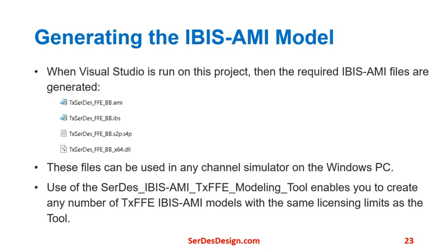When the Visual Studio is run on this project, then the required IBIS-AMI files are generated. These files can be used in any channel simulator on the Windows PC. These are the AMI file, the IBIS file, the S4P file, and the DLL file. Use of the SerDes IBIS-AMI Transmit FFE Modeling Tool enables you to create any number of Transmit FFE IBIS-AMI models with the same licensing limits as the tool.